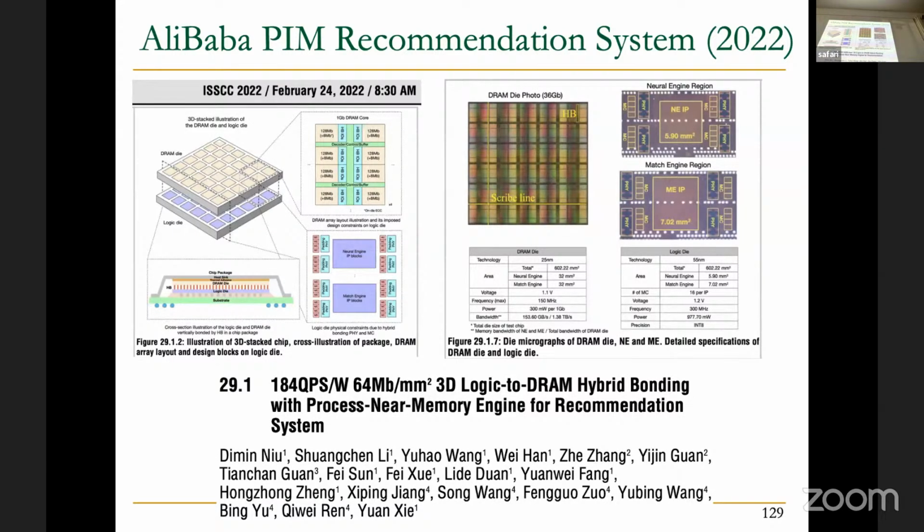Interesting innovation in this processing near memory engine from Alibaba is that they use this hybrid bonding technique, that is the fabrication technique to glue the two layers and connect them together tightly in order to enable and to allow high bandwidth between the logic layer and the DRAM layer.